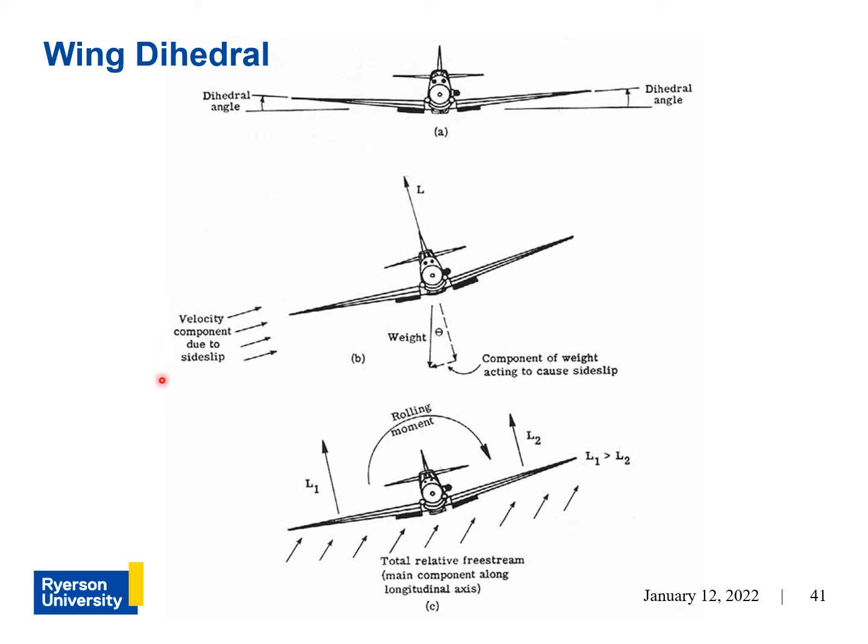So when an aircraft with a dihedral is disturbed from level flight, like here, the aerodynamics of the dihedral will cause a restorative rolling moment that will bring the aircraft back to level flight. And that's just the positive consequence of having a dihedral.